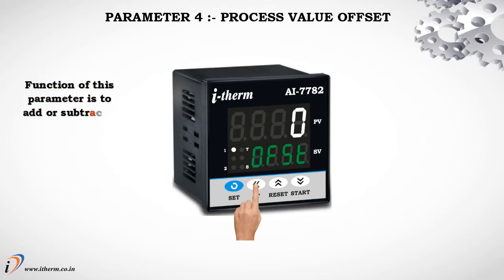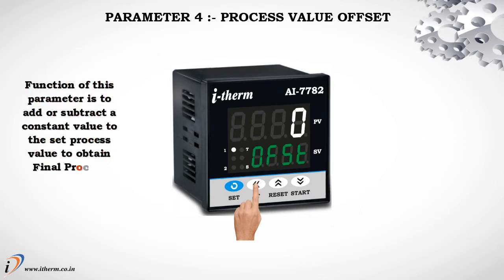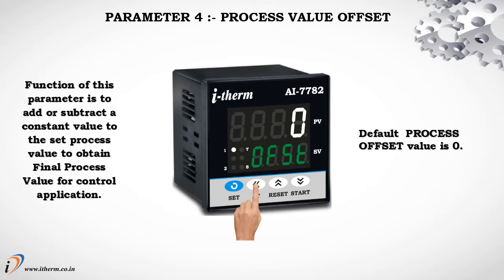Parameter 4, Process value offset. The function of this parameter is to add or subtract a constant value to the set process value to obtain the final process value for control application. Default process offset value is 0.